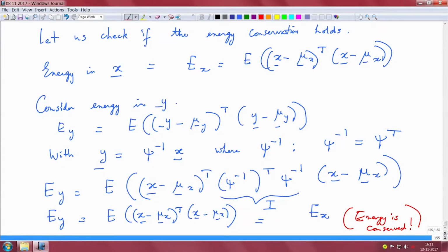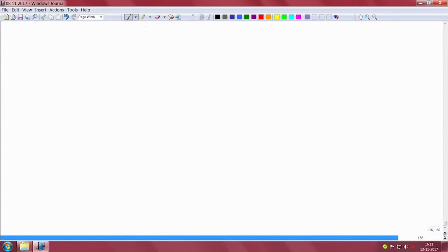When you do these transformations, you do not want to lose the original energy in the signal. The energy has to be preserved, but you decide what components you want to throw off, right. You decide how much of the energy you want to retain, and depending upon your threshold you decide what you can do with the representation. So, this picture should be very clear in your mind. Now, with some of these properties that we saw, we will motivate towards the derivation of the transformation.